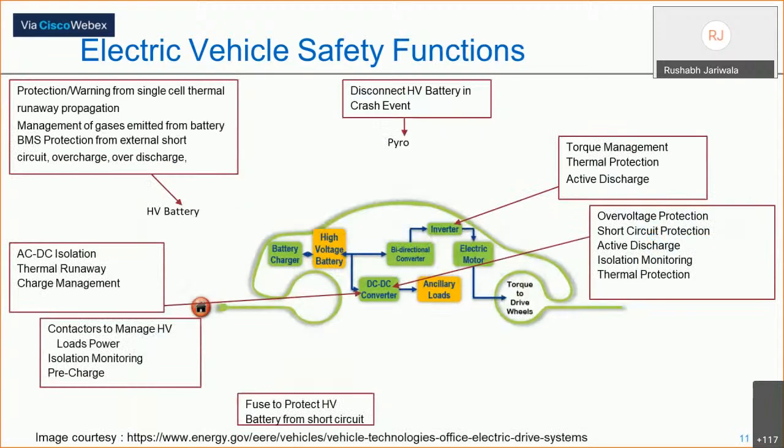Okay, so now I will explain some of the critical components and some of the safety related features related to them. So I'll start from here. There is a pyro switch next to the HV battery. That HV pyro switch acts as a small, I would rather say, fuse. Let's use the word fuse, but a fuse with a contactor.